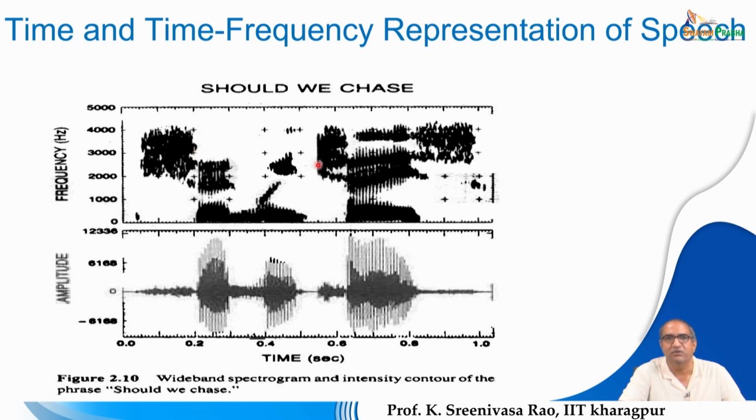More detail can be observed in the spectrogram. You can see sh is an unvoiced sound, so you see a noisy pattern. There is no regular pattern. Noisy pattern means we have energy at higher frequencies, but no systematic pattern. The energy is borne only by the high frequency components.